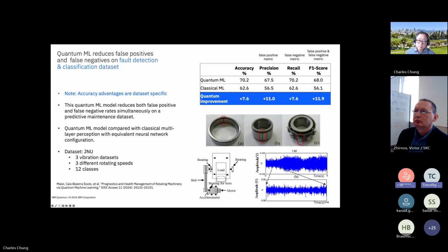Normally in ball-bearing defects, which I've done a lot of work on, we take the Fourier transform of the time series and get the individual frequencies, right? And we can calculate whether that frequency corresponds to a particular defect, like a defect on the inner or outer race, because it's calculated based on the RPM and the geometry. Sure. Is the quantum doing some type of frequency analysis to figure out where that defect is, or how does that work?